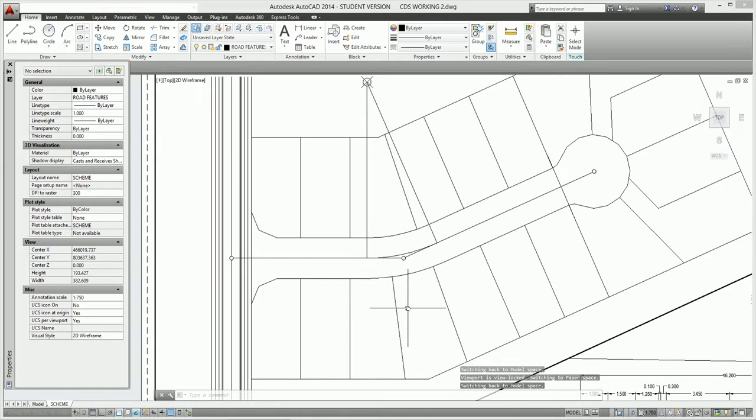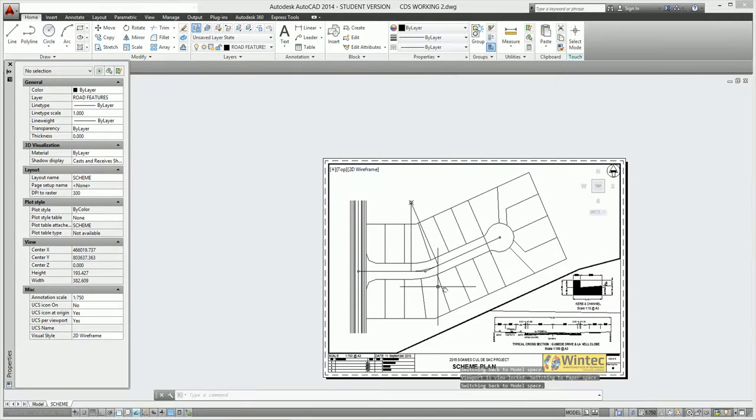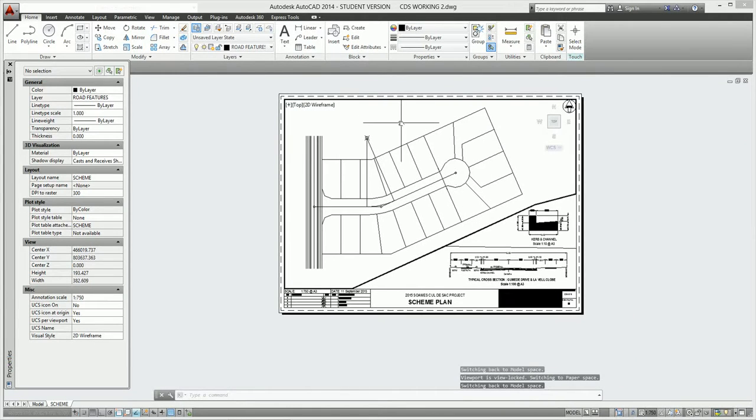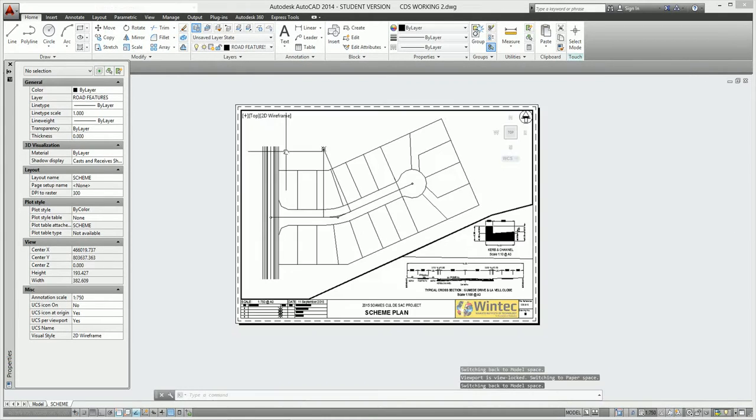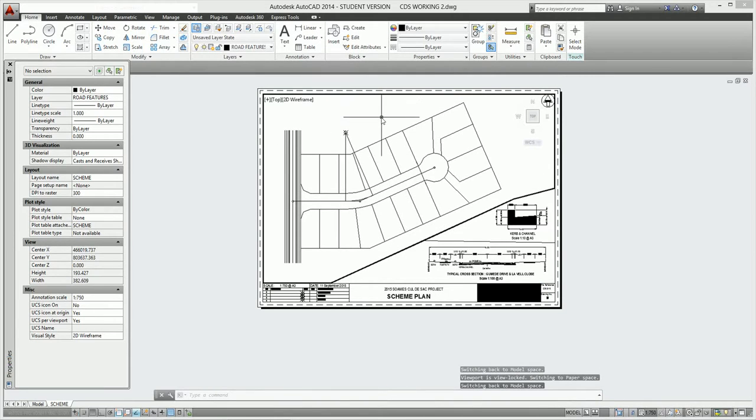I've got up to around about 10 minutes now with this video, so I'm just going to stop there and move on. I'll create another video where I'll start to show you how to work with the curvature. But the main thing to get out of what I've done here is first of all set up that curve there, and got my typical cross section and curve profiles all set up, and we're all ready to move. So yeah, we'll just go with that.